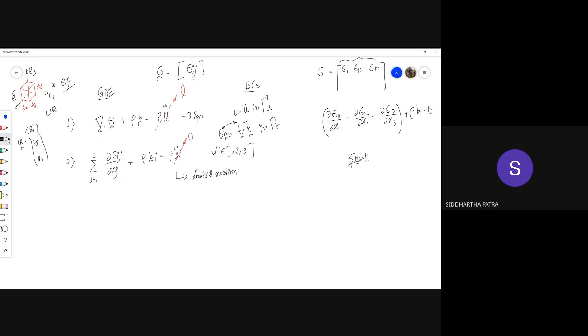Imagine the cantilever beam, the free end, whether you apply a concentrated force or a concentrated moment or nothing, whatever the case may be, you know that information about the free end. So in gamma t, you know the value of the traction. Here, I'm referring to what type of forces I am putting into the mechanism. The meaning of these two equations is that these two are known to you.